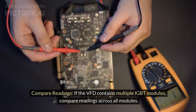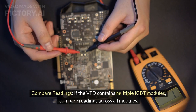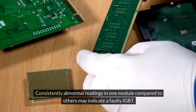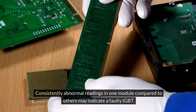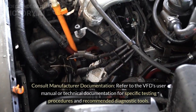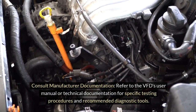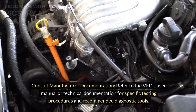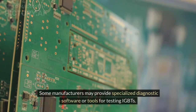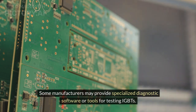Compare readings. If the VFD contains multiple IGBT modules, compare readings across all modules. Consistently abnormal readings in one module compared to others may indicate a faulty IGBT. Consult manufacturer documentation. Refer to the VFD's user manual or technical documentation for specific testing procedures and recommended diagnostic tools. Some manufacturers may provide specialized diagnostic software or tools for testing IGBTs.